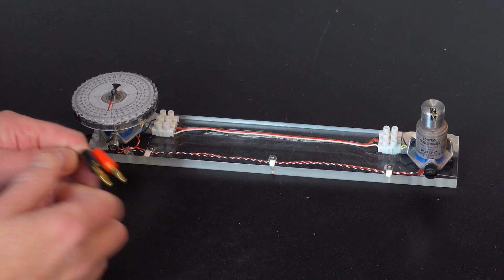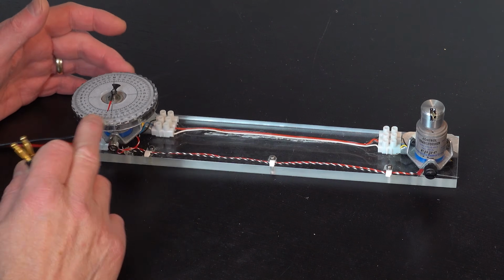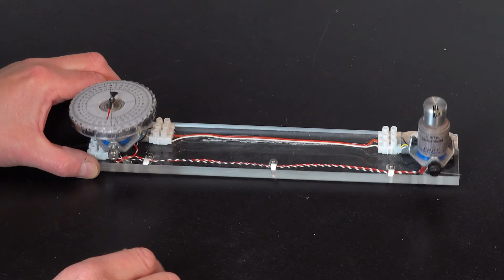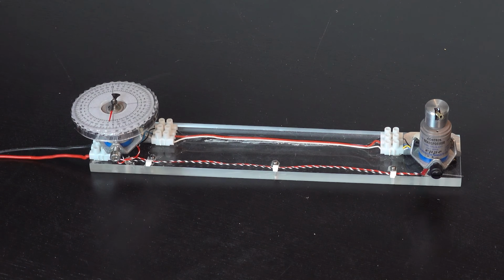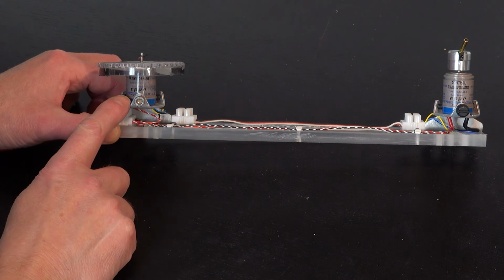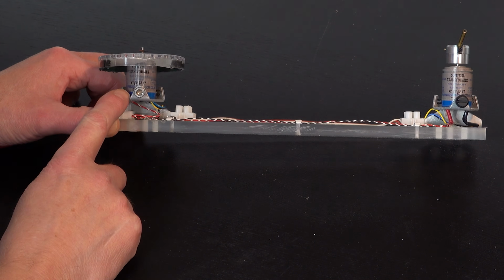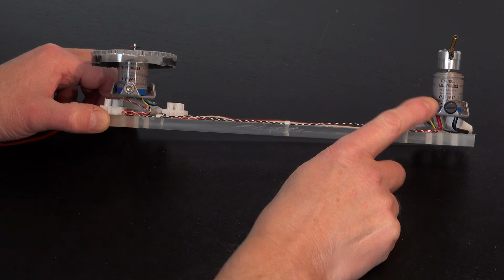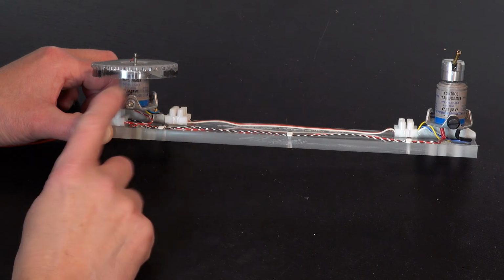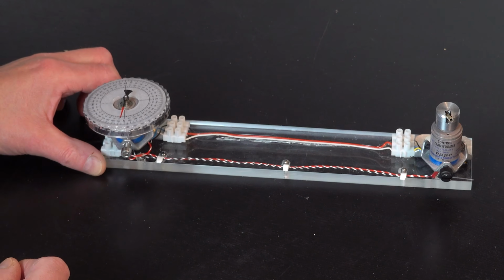Typically, a basic system like this consists of a transmitter and a receiver, both of which contain a set of 3-phase windings. The transmitter is connected to a shaft or other rotating device, in our case a bearing needle, and the receiver, here connected to a gun turret, can be at a remote location that can be anything from a few inches, as here, to a few miles in the case of a real coastal gun battery.